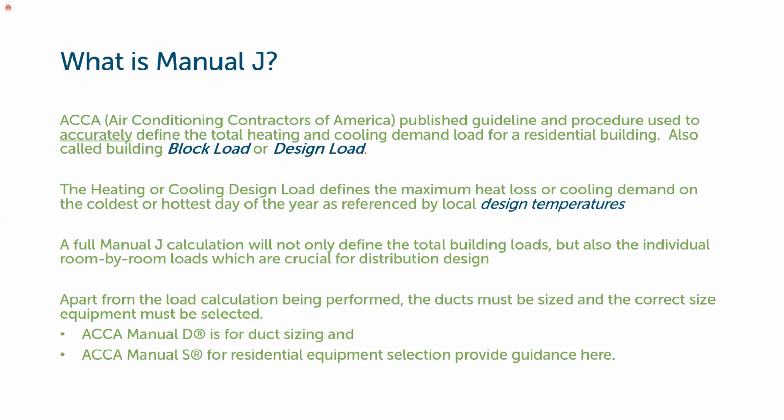It's distribution design, but as a basis here, and as you can kind of tell from the name, Manual D is focused on ducted heating and cooling systems. The basis design for room by room load calculations is important and crucial for hydronic system design also. And also ACCA Manual S is a manual we're using for actually sizing and selecting appropriate equipment for the loads that you come up with for the building.